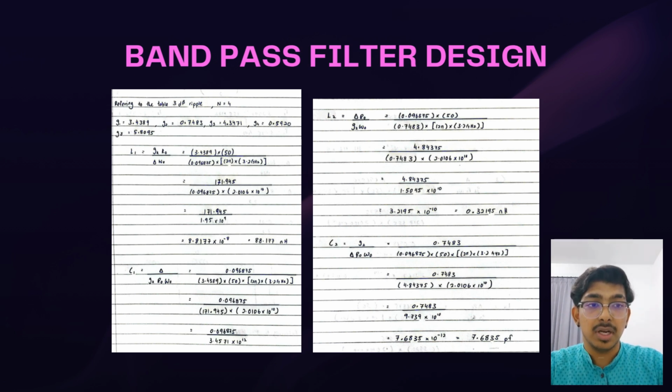Once all component values have been verified, the complete circuit is constructed and then simulated using ADS to confirm that the theoretical calculations match the expected frequency response. In this slide, we can see we have calculated the inductance and capacitance, which are L1, C1 and L2, C2.